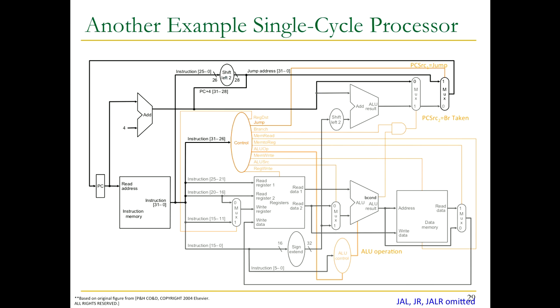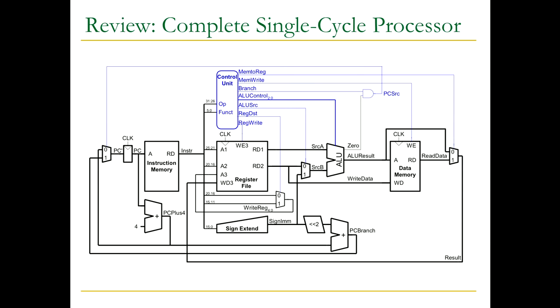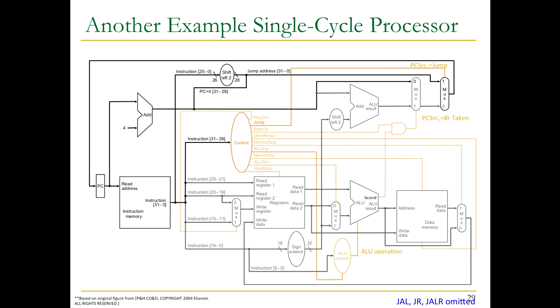This is another example of a single-cycle processor. I just want to give you an example because there's only very few ways you can design a single-cycle processor, actually. This is from another book. This is from Harris and Harris, which is your textbook, which was discussed. And this is from Patterson and Hennessy, their computer organization book, which has a few more instructions over here. But if you look at it, the design is very, very similar, right? In fact, you see 3 adders over here also, and 2 memories over here. Now, these guys probably looked at each other also when they were designing the machines, but that's beside the point. Single-cycle machines, you don't have a lot of freedom to design.